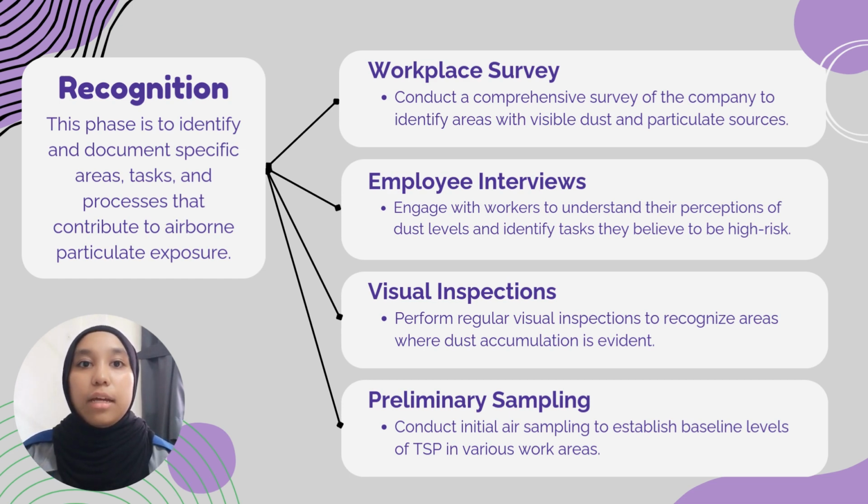And there is 4 recognition that we can get from this assessment, which is the first one is workplace survey. It is to conduct a comprehensive survey of the company to identify areas with visible dust and particulate sources. Second one is employee interviews. We interview the employees and it is engaged with focus to understand their perceptions of dust levels and identify tasks they believe to be high risk.